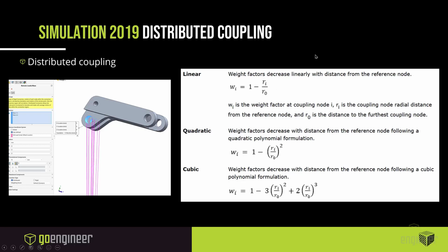So here you saw that I had a little ping over the rigid versus distributed. Rigid just means you're applying that force at a certain distance to that part, and it doesn't include the linear, quadratic, or cubic adjustments for the weight factor. Of course, once we start applying these to the fixture or the nodes, this will change our result because we are now adding accuracy to the type of behavior that part is going to act on our part in question.